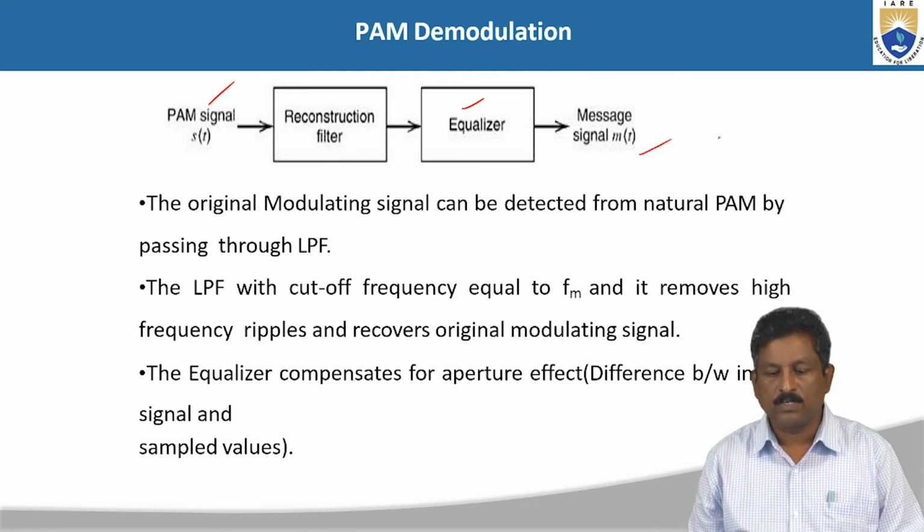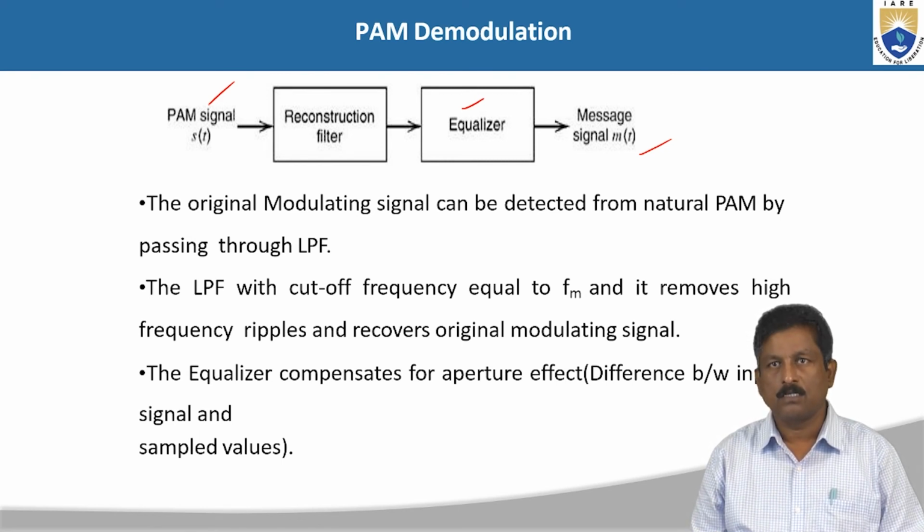So let us see what is the difference between the modulator and demodulator. The modulator combines both input signals, that is the modulating signal and carrier, enhances the high frequency components and transmits. Whatever signal is transmitted by the modulator, the same signal is received as an input signal at the receiver part, that is the demodulator part. Here again, by using the same frequency of the carrier signal, with the arrangement of the low pass filter, you can realize our original modulating signal. That is the essence. So this is about the generation and also demodulation.